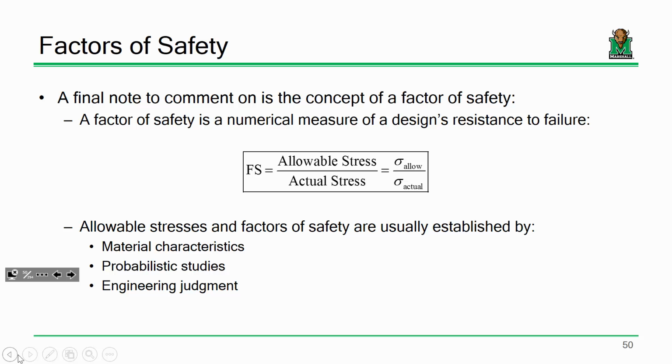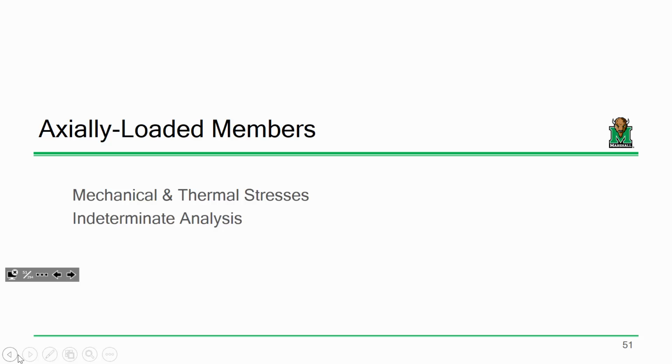Remember that truss example? And I said, well, what if sigma allowable was 12 KSI? And my man here in the back said, oh, I ain't feeling that too much. Well, that's because he was thinking about a factor of safety. Without even codifying the idea, technically it was good, and that's pretty close, okay? Now, what is the factor of safety for you versus you versus you versus you? Well, that's a function of A, the design codes that you're using, and B, a little bit of engineering judgment, okay? That's why you get a stamp, so that you can use your judgment to appropriately design things.